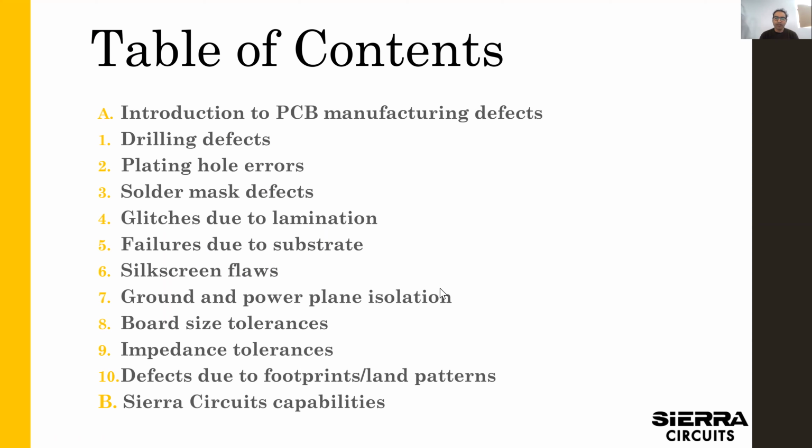So the number one area where you can have a PCB defect is in the plated hole wall. This is where all the failure modes are likely to occur, or very often they do occur. These are the serious failure modes, serious defects where if you're building an airplane, the electronics can fail. Or you're building a self-driving car, the electronics can fail. You don't want that to happen. So having a very well-designed board from vias is really critical.